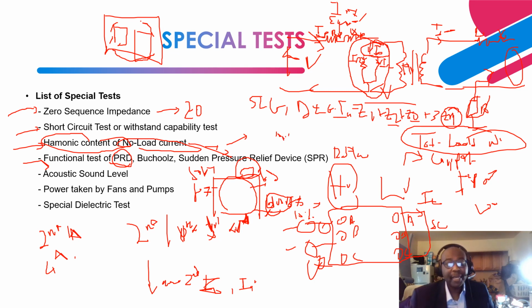The worst-case short circuit current is calculated, right, based on the impedance of the transformer. And based on the time duration of all these protective relay devices failing, the electromagnetic force is determined, and based on that the pressure equivalent to the electrodynamic force is determined. This determines the set point of this pressure relief device. So when all these protective relay elements fail, that is when the pressure relief device opens up and expunges all the oil onto the floor.